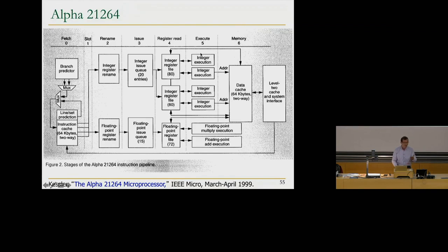units. Now, they were so tight on timing that, in this case, they duplicated the register file. They have two copies of the integer register file, because they wanted to be able to send two instructions here and two instructions here. We didn't talk about the concept of superscalar execution. We're going to see that. So far, we've executed maybe one instruction, but you can actually do two instructions here and two instructions here.